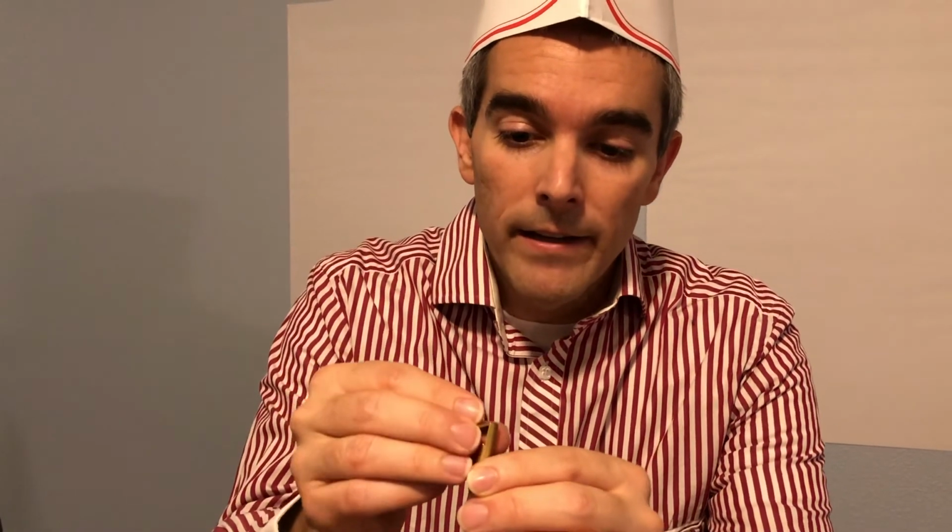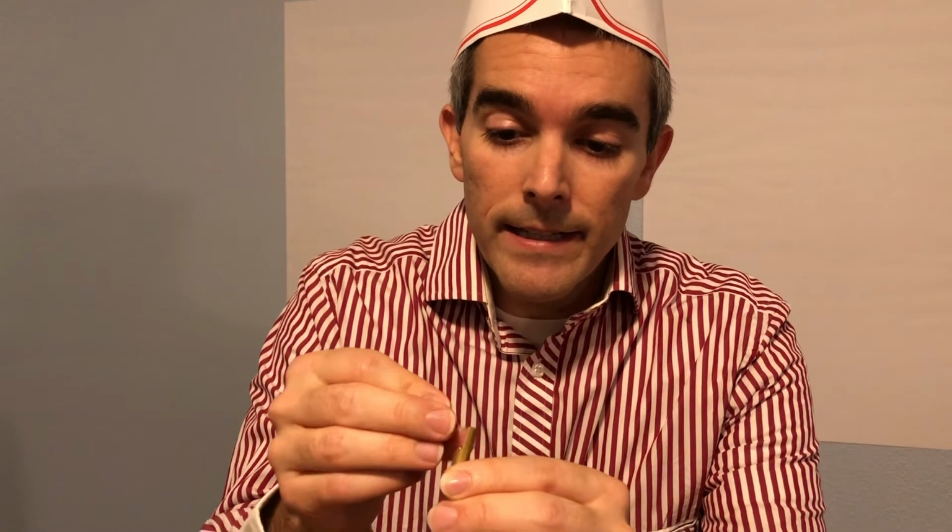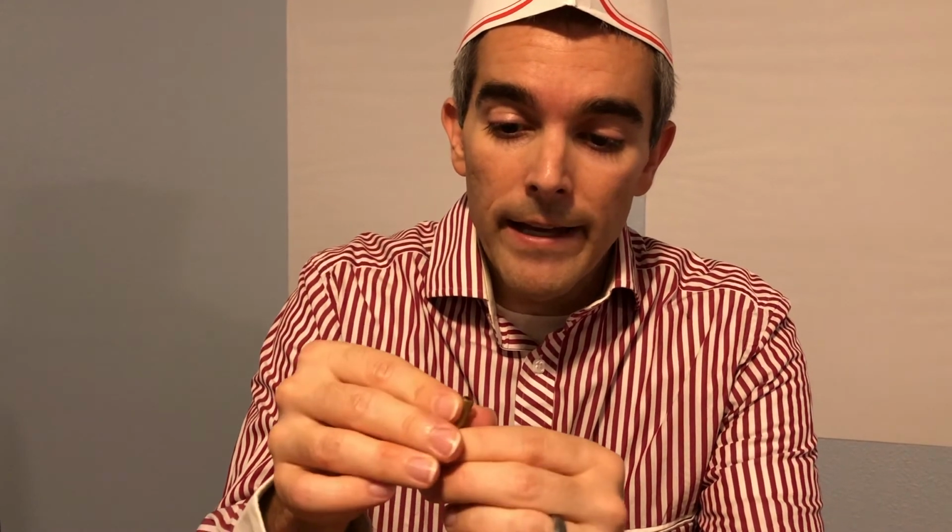You can see along the edge here, it was kind of a brittle fracture. It follows a little bit of a helical path because it was under shear stress that ultimately caused it to fail. This is a good example too of a cylindrical shape that we might be doing a lot of our analyses on, especially when we talk about calculating J and polar moment of inertia and stuff. So it's a good example.